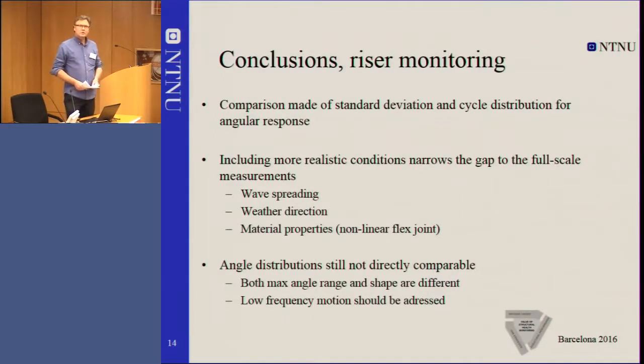So conclusion from the riser monitoring, that you have made comparison between the standard deviation of the cycle distribution for angular response, and you can also include more realistic conditions and narrow the gap between full scale and measurements: wave spreading, weather direction, material properties, nonlinear flex joints.